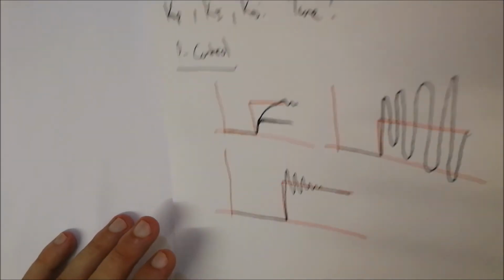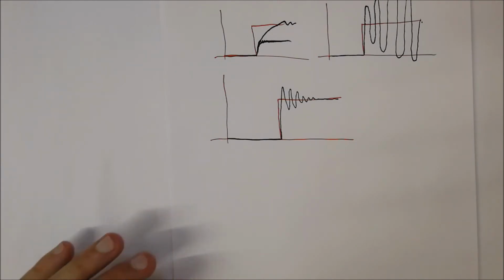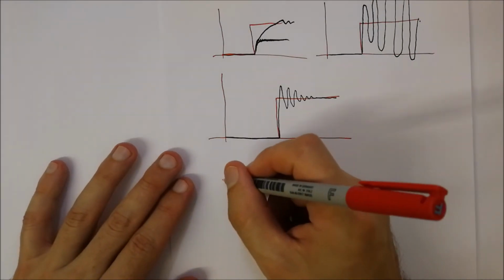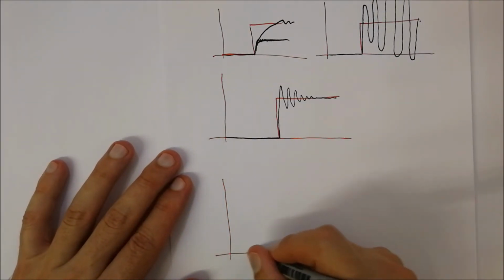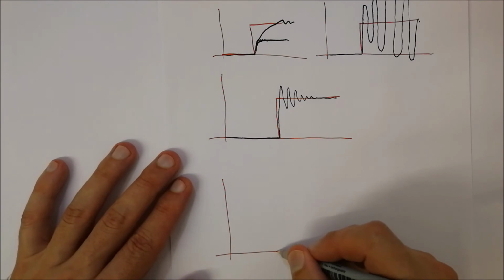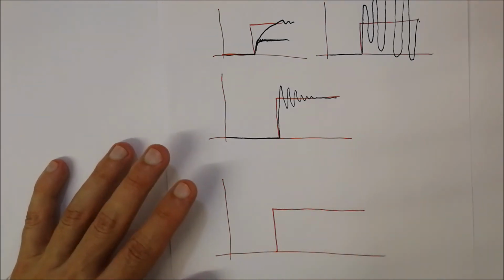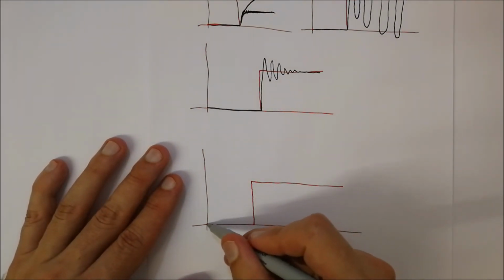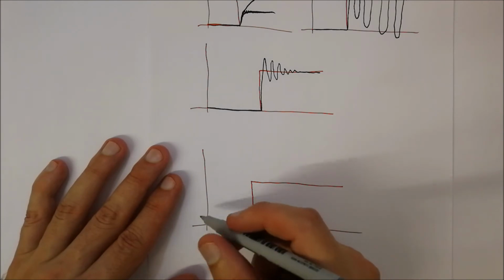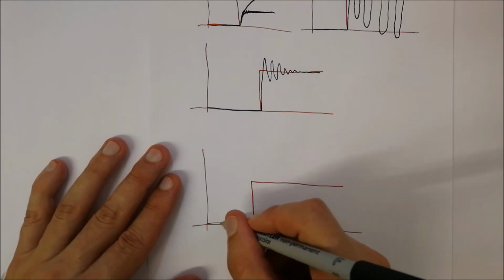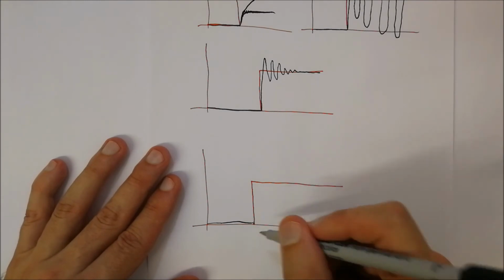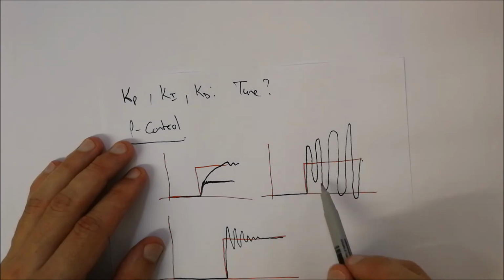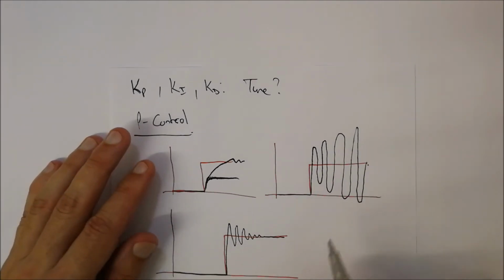Okay, so how do you go about tuning your proportional controllers? Well, essentially, it is a trial and error type of scenario. You've got your monitor, your output that you want, and you give it a certain set point that you want to achieve. You keep on increasing your proportional value, and you monitor the value of the proportional control before it starts oscillating and going out of control.